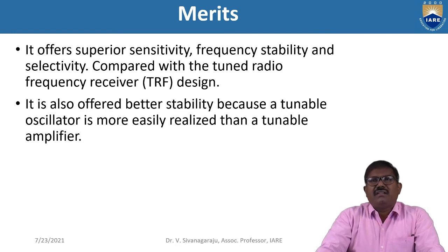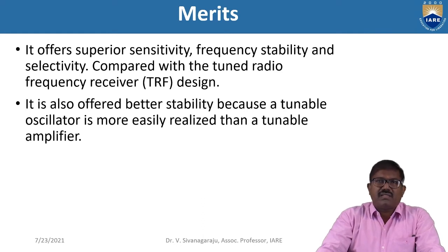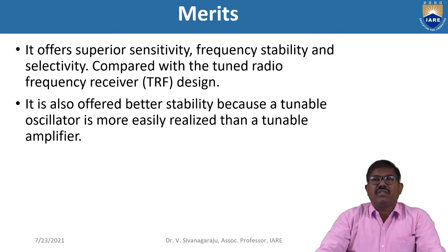And the second merit of this super heterodyne receiver is that it also offers better stability, because the tunable oscillator is more easily realized than a tunable amplifier. So these are the merits of the super heterodyne receiver.